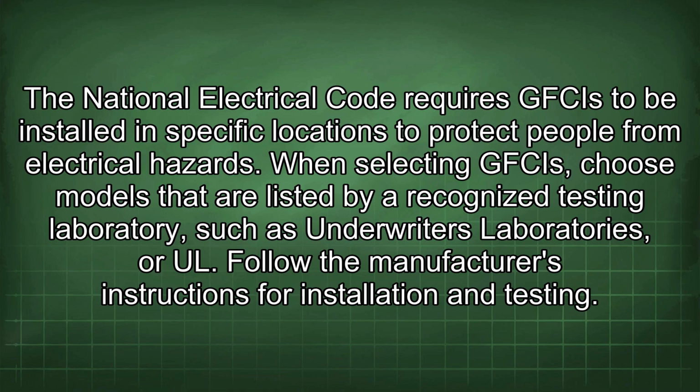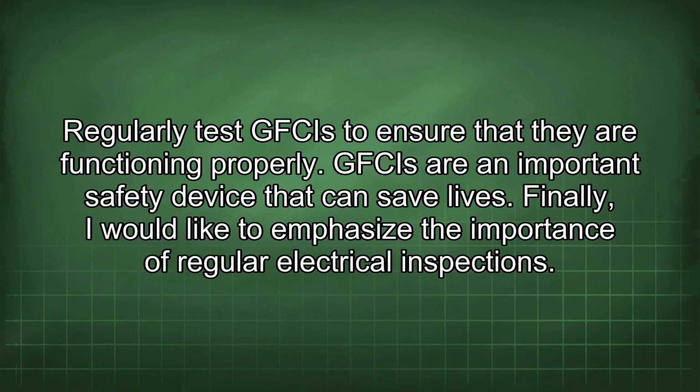When selecting GFCIs, choose models that are listed by a recognized testing laboratory, such as Underwriters Laboratories or UL. Follow the manufacturer's instructions for installation and testing. Regularly test GFCIs to ensure that they are functioning properly. GFCIs are an important safety device that can save lives.